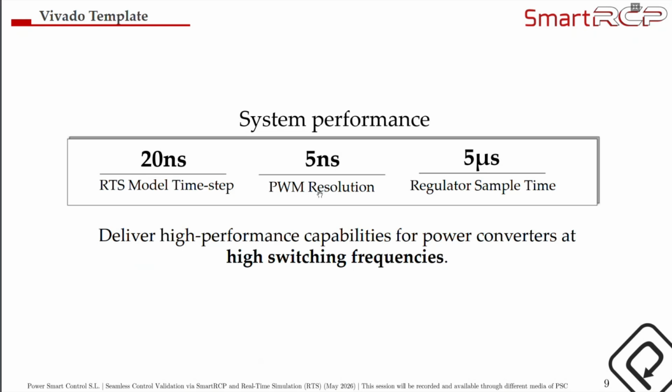We also have 5 nanoseconds PWM resolution, which is vital for correctly operating the phase shift between the bridges of the dual active bridge converter.